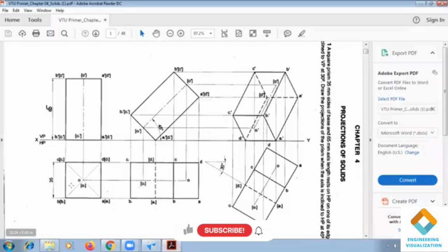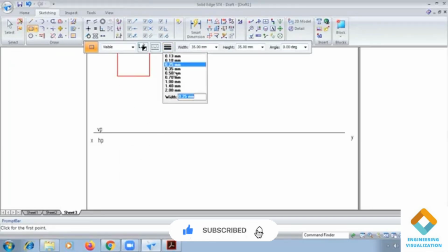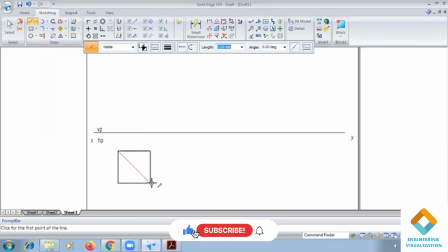So first position is in a square of dimension 35. The thickness is 0.50. After this, we have to draw the diagonal lines to find out the center of the axis. These lines have to be thin lines in case of a prism.